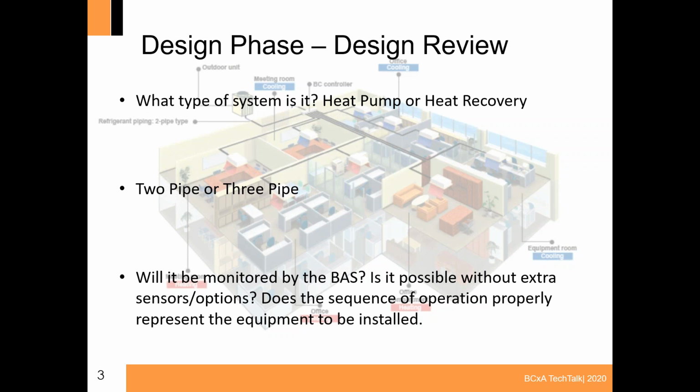So next is a 2-pipe or 3-pipe system. A 2-pipe system is done by one manufacturer only, and basically sends a multi-state gas-liquid to the branch selector to be distributed to each indoor unit based on cooling and heating requests. The 3-pipe system is used by all other manufacturers. There are advantages and disadvantages to each, but we don't need to dive into those, since we don't make those unit selections. We just deal with the aftermath. So we just need to know the differences.